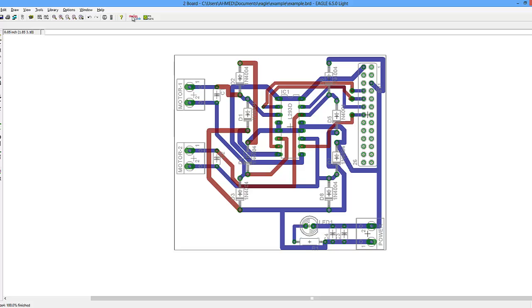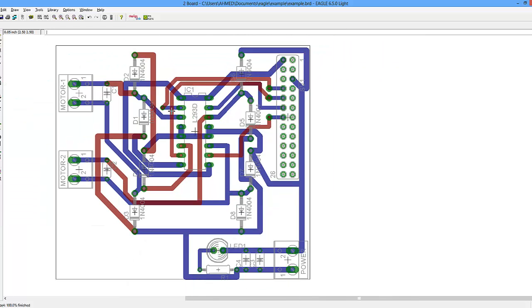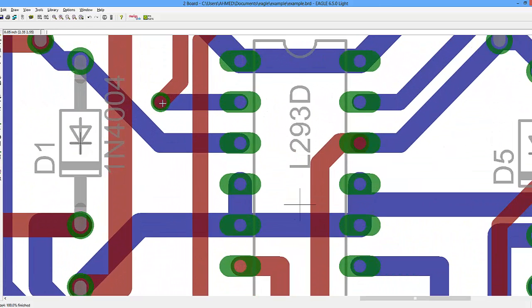If you observe here, for example, these are vias that I had control of and placed. You see, but this is a via placed by the auto router. Now the dimension inside the hole is 0.8 mm, but the width of the via is not the same.